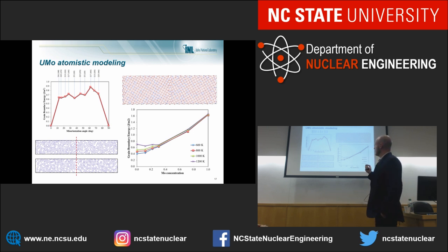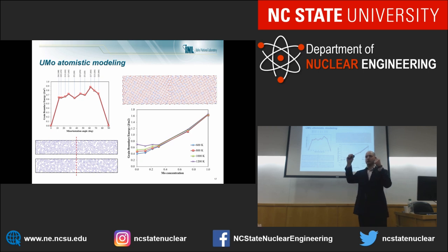The other thing that we did is try to perform this actively. So instead of just doing a static study on the grain boundary energy and inferring the results off of it, we did a combined Monte Carlo MD study where we're performing switches of atoms and accepting the switch if the energy of the system is reduced, and also accepting it given a certain Monte Carlo probability of accepting the switch.